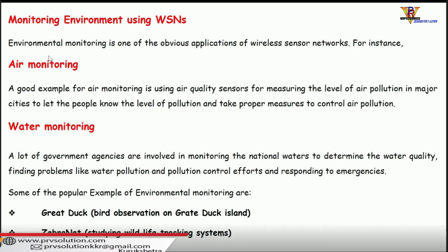Okay, the simple thing is simply how we can determine the quality of water. One thing you might be aware of is the TDS level. In the market, cheap TDS sensors are available. Just by dipping the electrodes of the TDS sensor, you will get the TDS level. And according to WHO, if the TDS value ranges from more than 50 to, let's say, 600, then it may be safe for drinking.